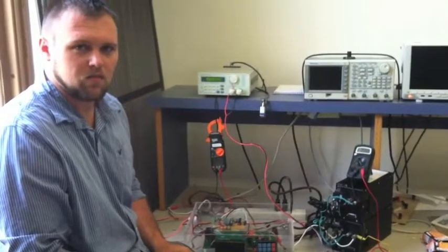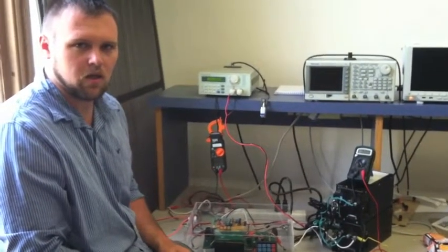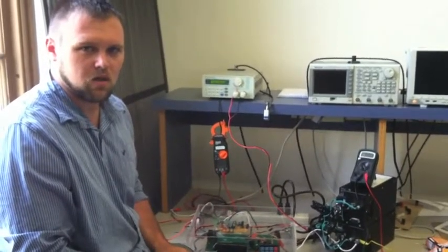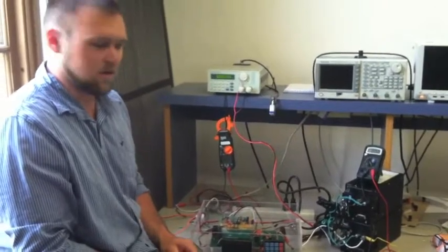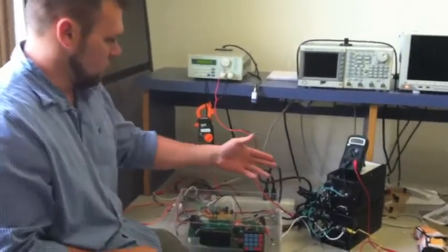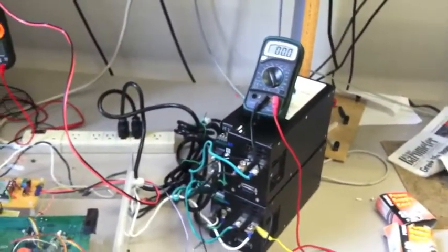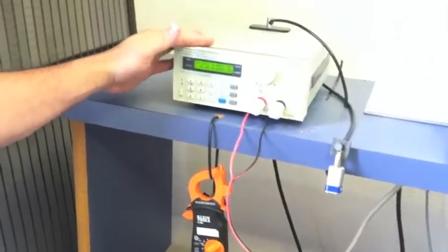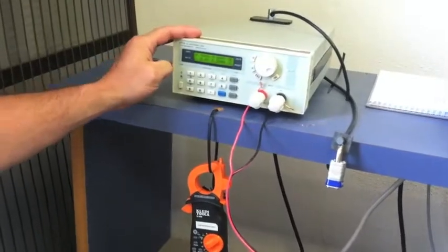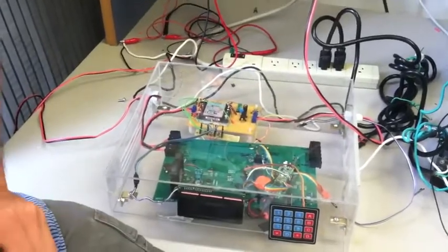We're Group 21, the maximum power point tracking charge controller, and one of our requirements was that our charge controller can output 150 watts. So this is the 150 watt test. We have our power supply set up to 36 volts, which is input to this side of the charge controller. And then on the output we have a dynamic load that we will load the charge controller to 150 watts, approximately 10 amps. The DC to DC converter is nominally at 15 volts.